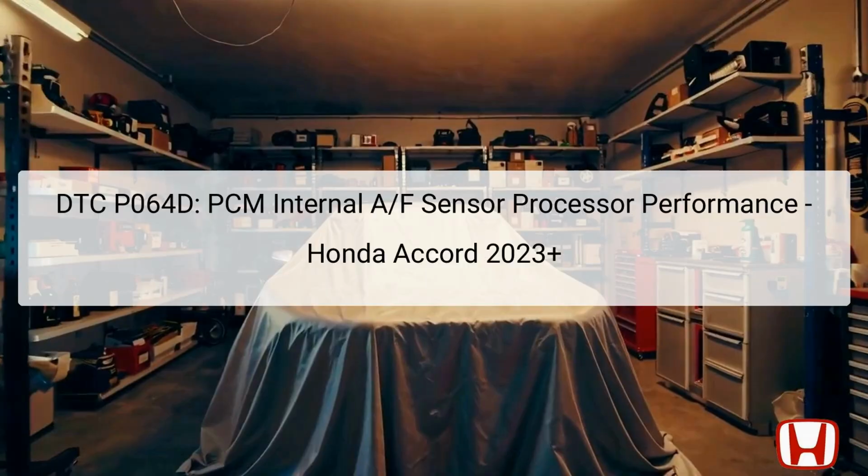The DTC P064D indicates a problem related to the Powertrain Control Module, PCM, internal processing for the air-fuel ratio, AF, sensor, specifically Sensor 1. This error occurs when the PCM detects an abnormality by comparing the input, IP current drawn from the analog signal interface circuit, ASIC, with the actual IP current. If there is a significant deviation, this triggers the DTC to be stored.